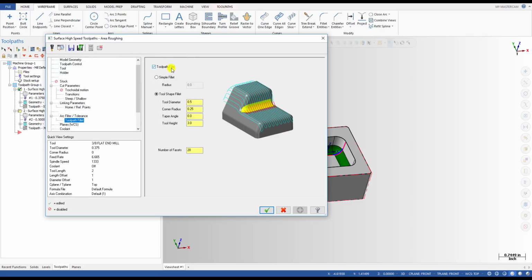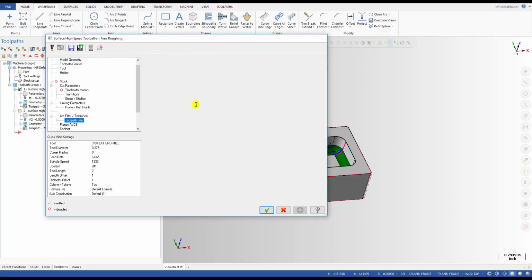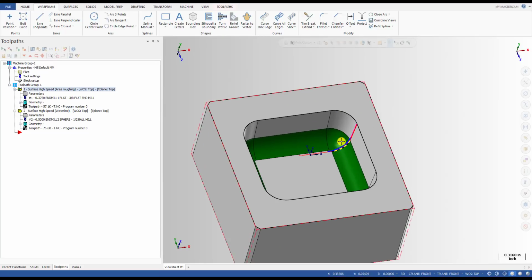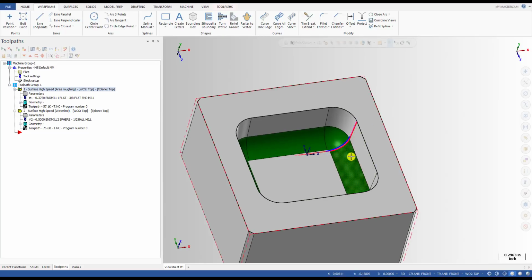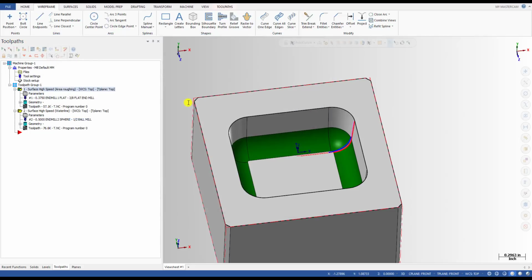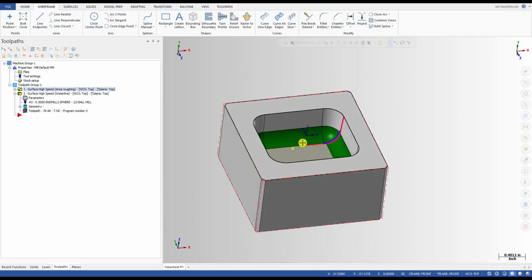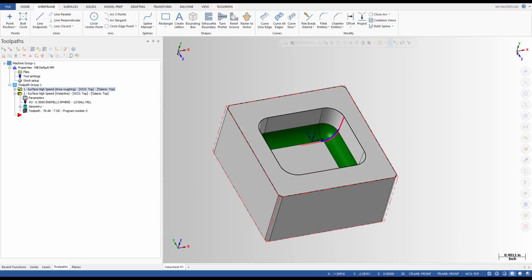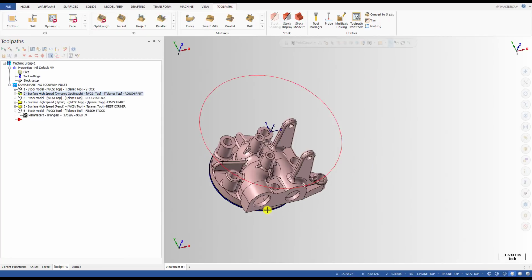That's the Toolpath fillet. So with this option, we don't have to modify the model to use a bigger tool for finish. We just input the value of the tool you want to finish the part, and everything will be modified automatically. Super. I love this function. Okay. This is the part for demonstration, and now we go to the part for case study.